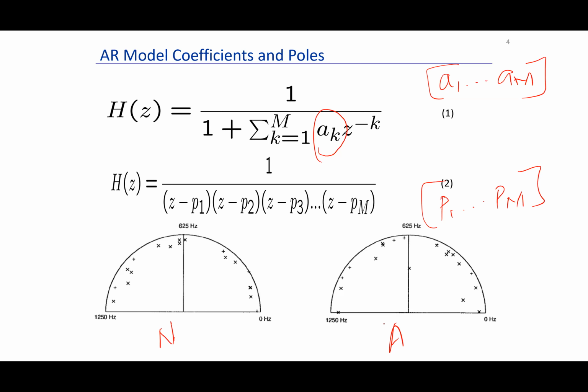You could go one step further. You could ignore some of the poles which are far away from the unit circle, because they don't really contribute to the spectral peaks. In any signal processing application, the features are quite prominent when you have spectral peaks, and spectral peaks come when the poles are closer to the unit circle. And it goes back to the first module that we learned.